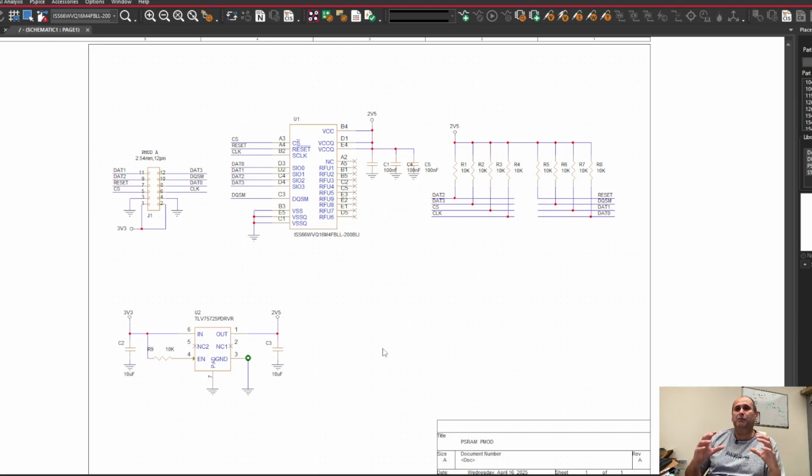Because the tricky part is that the moment you use the IOs, like DDR IOs, you can use ChipScope, which is some sort of internal logic analyzer, or integrated logic analyzer, ILA is called in the tools. The moment you use those IOs, you can't sample them from the inside. So a good technique is actually to feed them out and bring them back into the board on a different connector and sample there, so you see exactly what the memory sees. But anyway, we'll get to that in the next video.